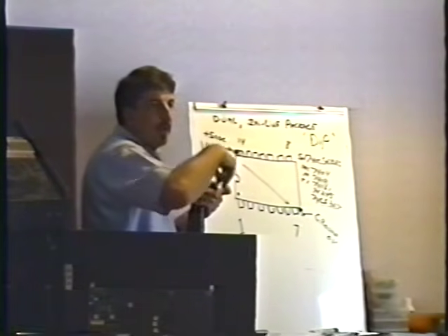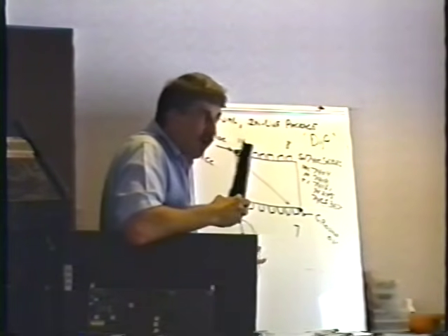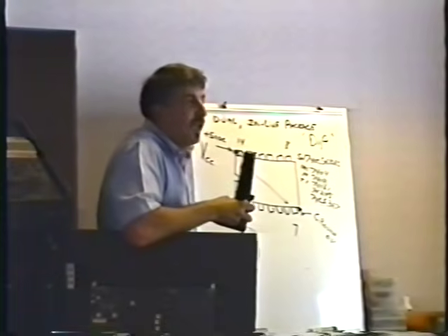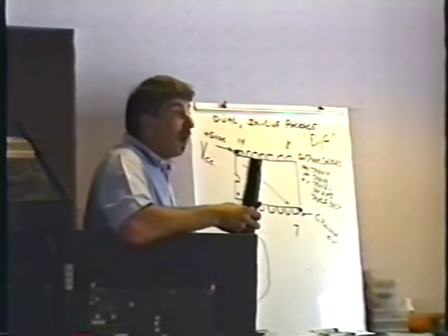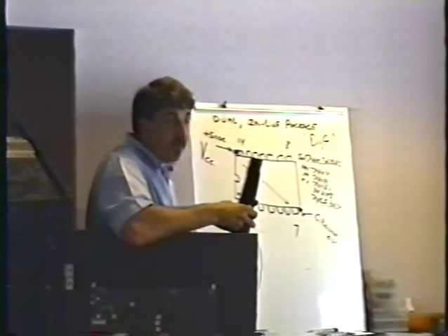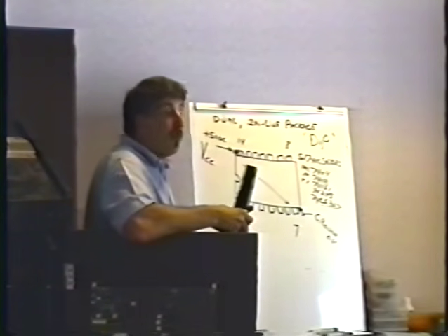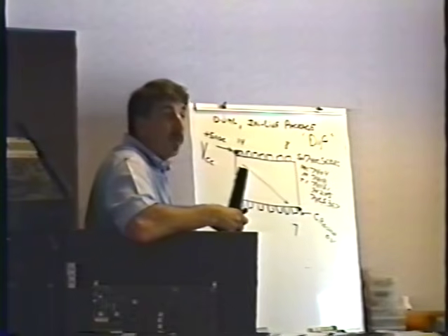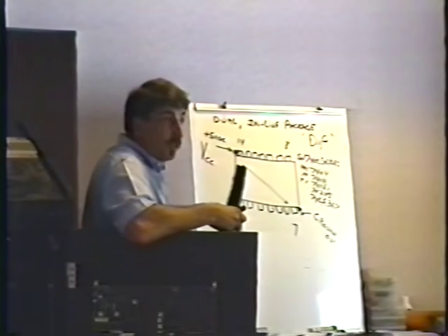just jam them in the corners, and with my meter there, I set the power supply to exactly 5.1 volts on the board. I don't care if it's 5.1 or 5.2, or 5.3 at the power supply. I want it to be 5.1 on the board itself. Does that make sense? That's really important.